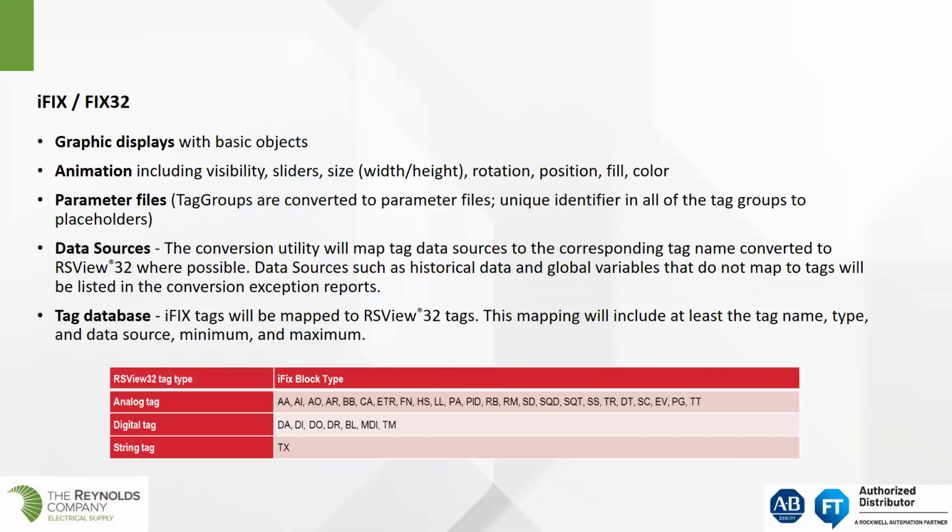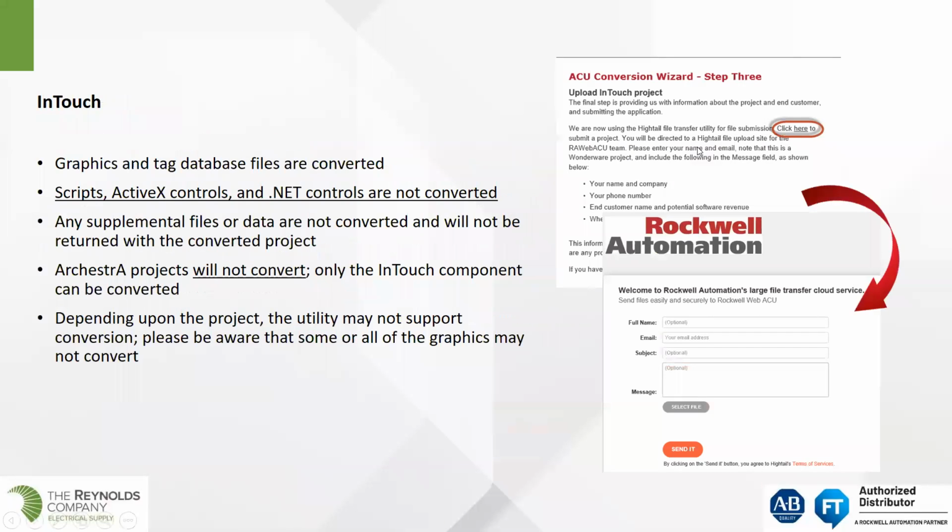Now the base tag database is converted, and in the diagram there, all the iFIX block types that you see, especially all the analogs, are converted to RSView32 tags. And then you can work with them in the tag database. Go ahead, Mark, next slide.